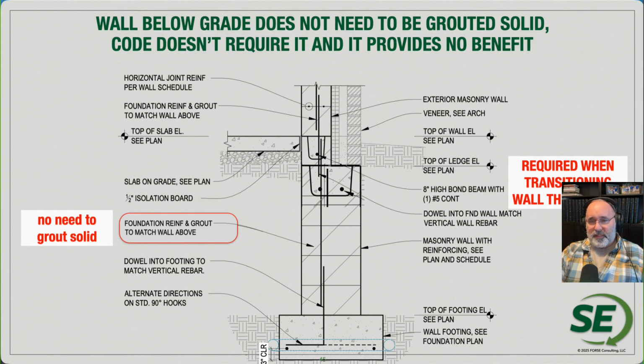Here you can also see two different bond beams being used. Again, the lower one is going to be important to make sure that we have that transition for the wall, if you do have the cavity wall elements coming down below grade. But then even carrying either the bond beam or at least a solid grouted course above, so that you can have those dowels all the way up to at grade. So the slab on grade condition is going to be important.